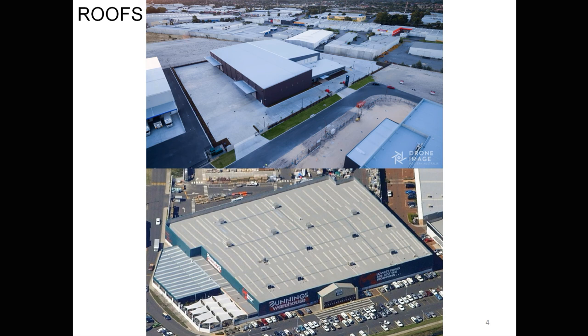Swati, did you have a question? Yeah. So that particular gutter and downpipe, does it work on a mechanical system? Probably no. The question was about the siphonic system. It's not a mechanical thing. Just by the shape of the entry into the downpipe from the box gutter, it forces the water into a certain pattern, which makes a bit of a whirlpool and sucks everything down much faster. There is a bit of a funnel happening, but it's got to do with how it goes into that funnel. Once it's set on a certain path, it just drags everything through. It doesn't need to be very much of a funnel. You think about a funnel, all the water goes straight down the sides. It's actually about directing water into that funnel so it spirals down.